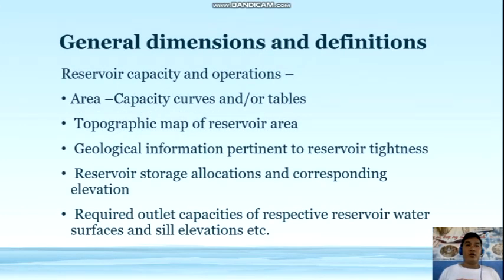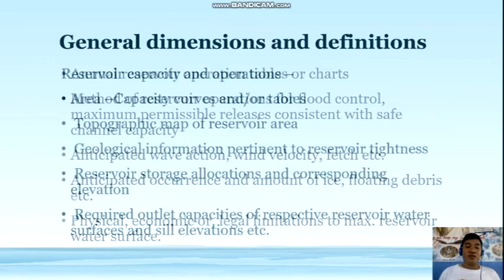Reservoir capacity and operations. This includes the area-capacity curves or tables, the topographic map of a reservoir area, the geological information pertinent to reservoir tightness, reservoir storage allocations and corresponding elevations, and required outlet capacities of the respective reservoir, water surfaces, and sill elevation, etc.